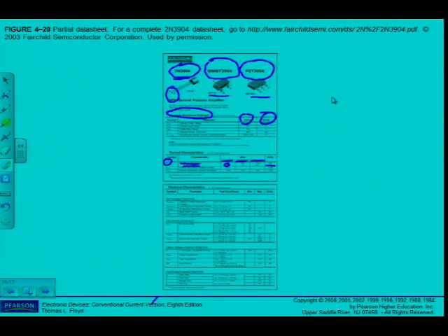Right, another important thing from the data sheet that I just want to point out is on the ON characteristics. The first thing there, the thing that we have mentioned earlier, HFE. What is HFE? Beta DC, no? It's a DC current gain. Now what is important, you can see on these tables are indicated minimum, maximum, and units. Okay, so it's regarding these tables down here. So what do I note for HFE?